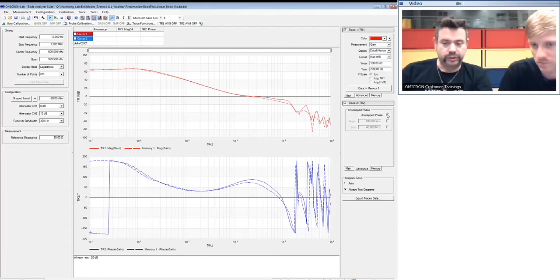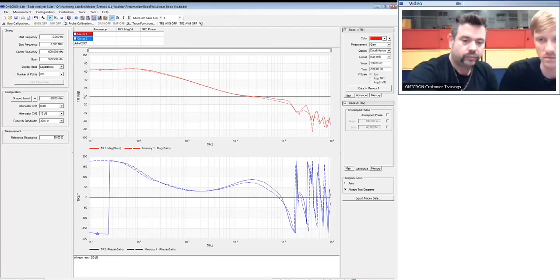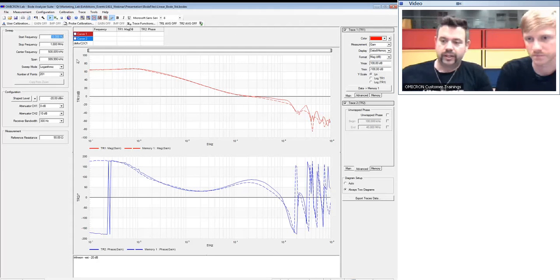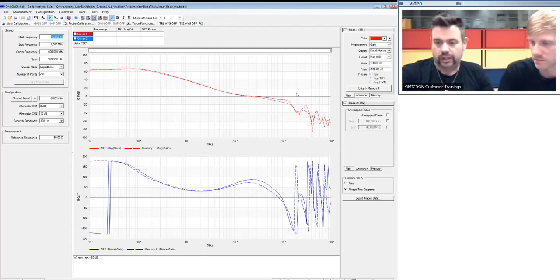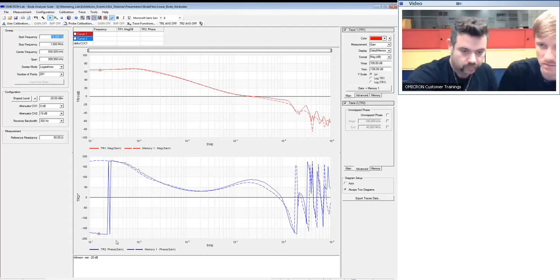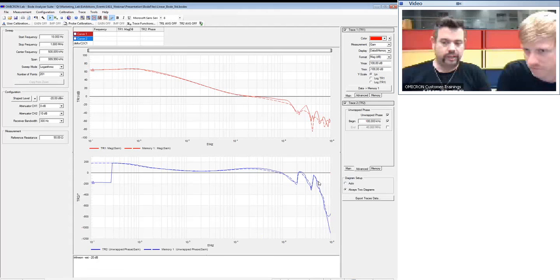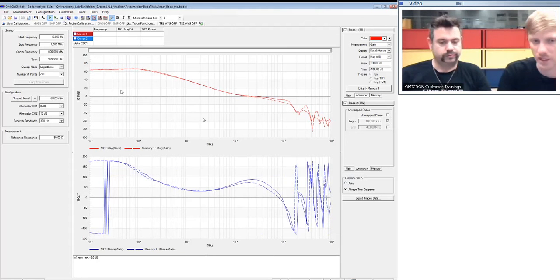We can use it for all discontinuities which happen after the point where the phase is getting from minus to plus. So, for example, if we set the start of the unwrapped phase to, let's say, 100 kilohertz, then it helps us at the end of the spectrum. Here you see a continuous phase. You see how the phase happens, but we cannot get rid of the first jump because this will shift our entire curve.